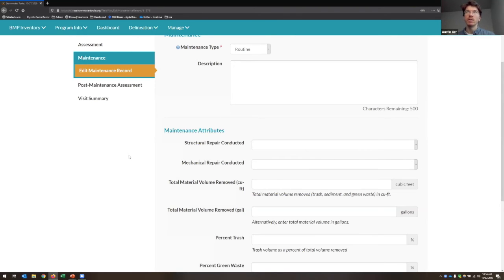And using either a design drawdown time or an underlying infiltration rate, we can use those two data points to enter our functional nomograph curve, which again was derived by doing thousands of runs of BMPs of various size, so that we can come up with a long-term estimate of how much volume, again, over like a 30-year period, that BMP will be expected to capture.